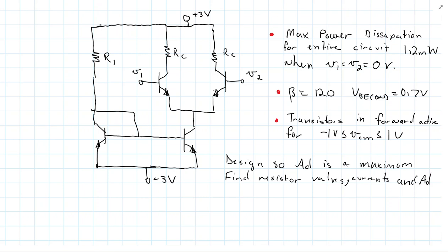First off, we should think carefully here. We know that this here is IREF, and with our differential amplifiers, we've been calling this IQ. Now remember, with this current mirror, beta is big enough that we're just going to go ahead and state that IREF is equal to IQ.